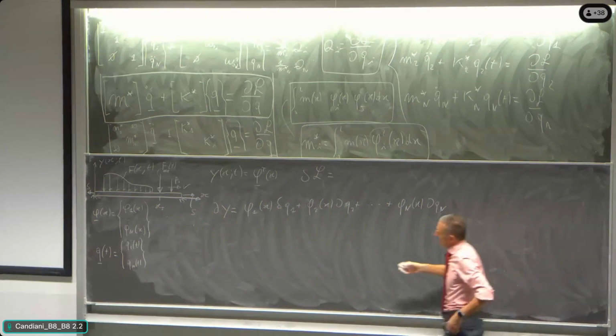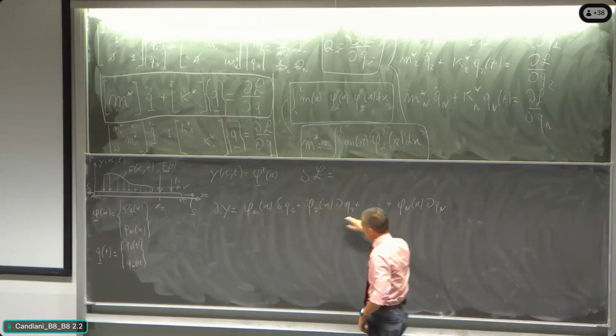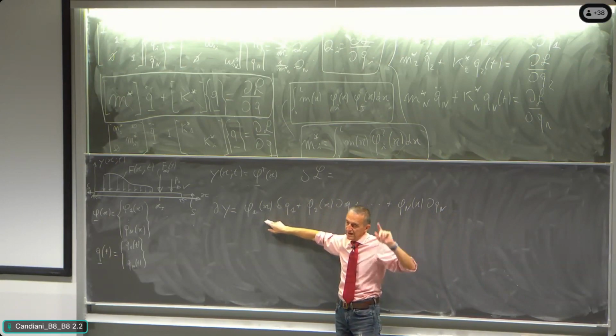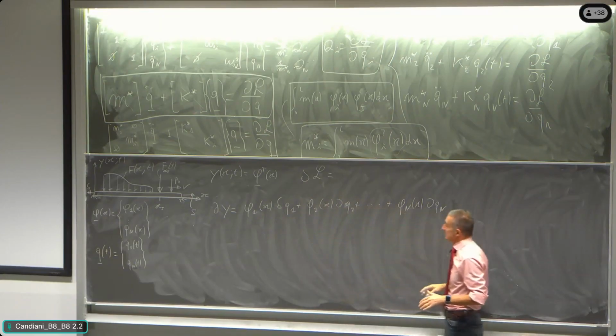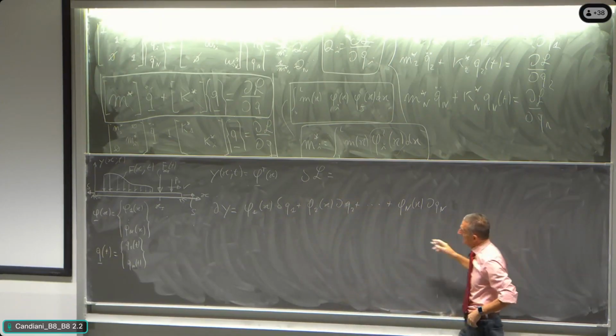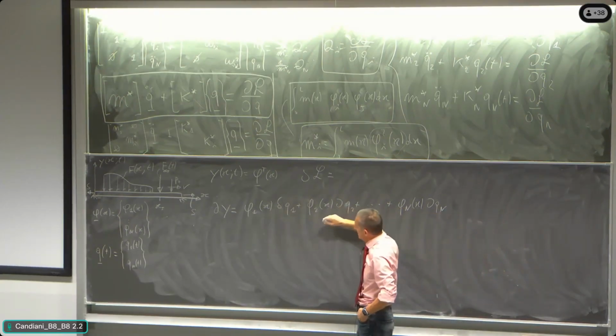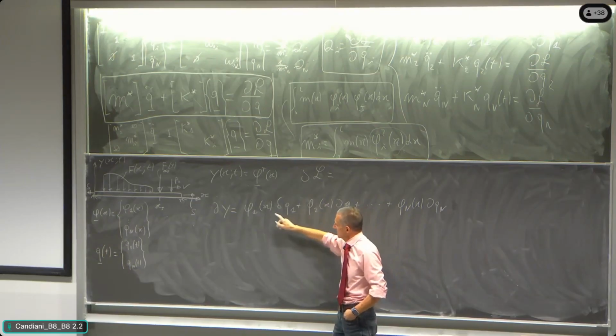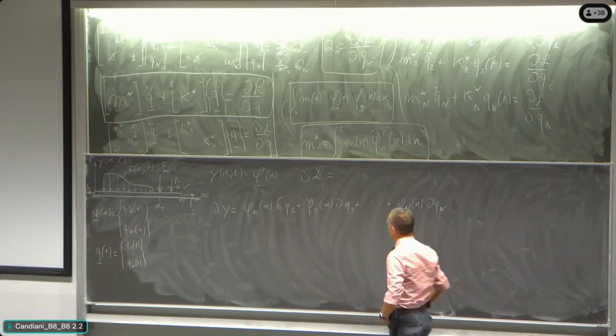But let's say that the virtual displacement is an infinitesimal displacement. It is compatible with the constraints because the modal shapes that we are using are fully compatible with the constraints, because they were calculated applying the constraints to the partial differential equation, the PDE, all right? And so it is actually an infinitesimal displacement distribution made by the superposition of all the modal shapes, each of them multiplied by the infinitesimal variation of the principal coordinate associated to the modal shape.